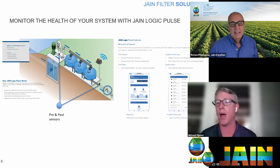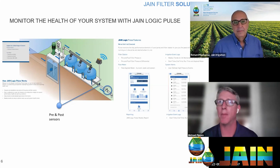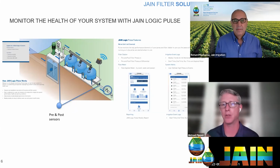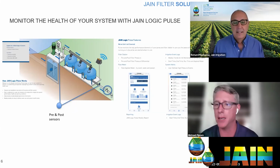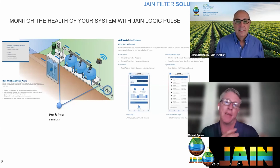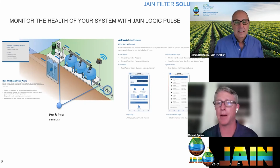And I say that in the sense, you go, how often do you flush? I don't really know the answer to that. I can kind of pull into my historical knowledge and say, if I've got a sand media filter and it's designed kind of around these parameters, and I've got a field in your area, maybe about every 4 to 6 hours, you can back flush it.